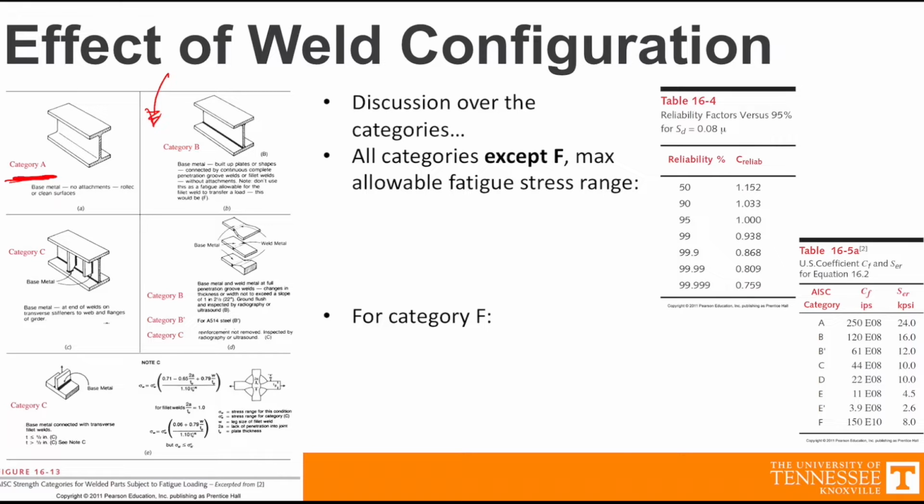One of the interesting things, when we look at the SN curves for welds, is that we don't use just the average of the fatigue strength values that were tested. What they actually did was use two standard deviations off of the average to build a window of these values. That allows us to have less of a reliability knockoff when we're calculating the fatigue strength of these materials. Two standard deviations is 95% confidence. So what you'll see over in this table is that for percent reliability, your 95% reliability is equal to a coefficient of 1.